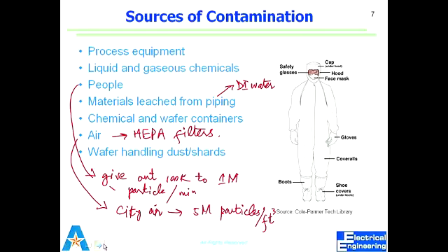This is the general environment, and then we have these sort of wash basins, you can call them, places where we do chemical processing. These are called hoods. A hood has a further isolated flow within it. A hood is nothing but a window. You open the window and there is a working room inside, and we stand there and do everything inside that hood. The local air is moving up, so whatever chemical I use, the fumes are not coming to me. They go within that localized airflow. So we maintain laminar flow within the hoods also.